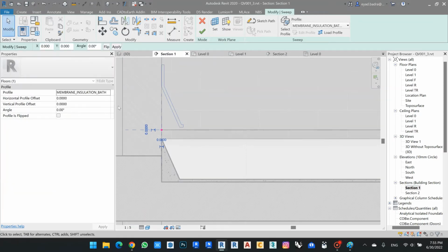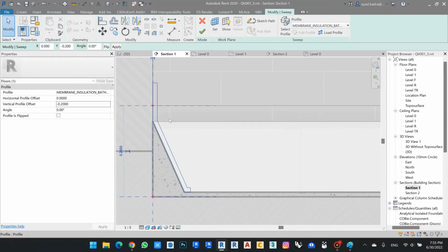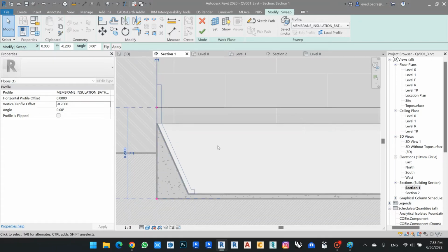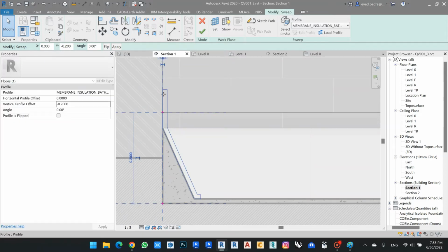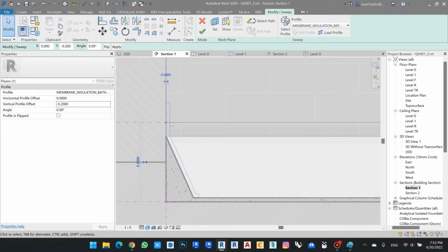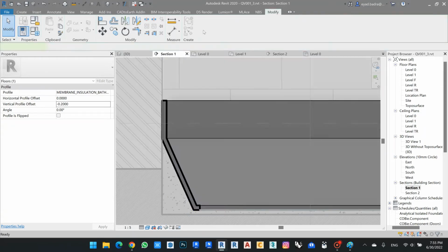As I can see here, let's first go back to 20 centimeter, and I already implemented a profile with all the dimensions after considering the dimension of the mortar from my profile family with 1 centimeter thickness. The layer already extends a little bit after the finish because it will connect with my mortar and with my ceramic in the wall, and this will guarantee the full insulation of my bathroom even after the level of the finish from the wall. And then I click OK.